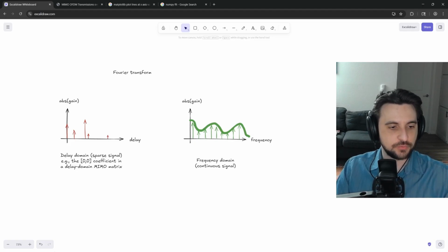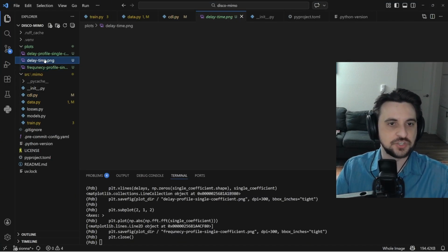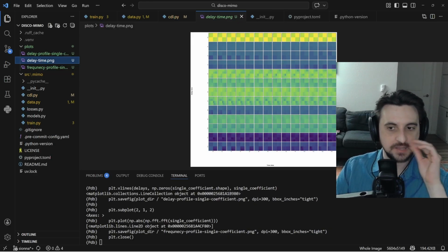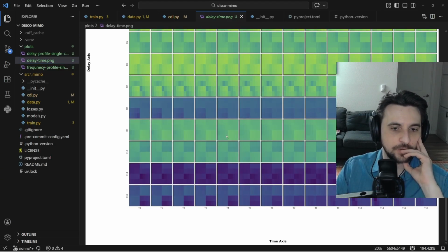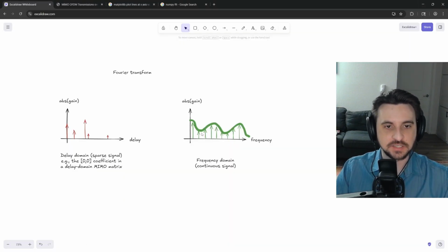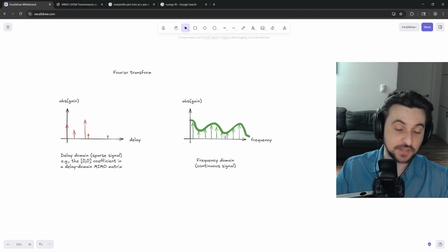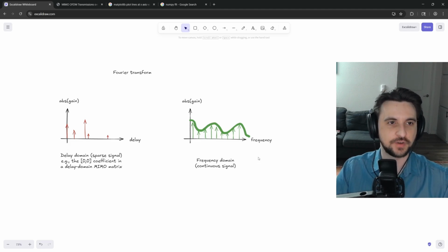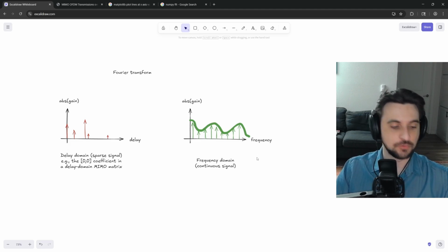So we started with data in a giant grid, and we picked the time point. Okay, then we converted from delay to frequency, and this is called OFDM, which is multiplexing users in the frequency domain. What happens is, these are now 1, 2, 3, 4, I don't know, 5. These are 9 different users. These are 9 cell phones. They're actually 9 cell phones. Like, this is literally how 5G and even 4G worked, and probably nothing's gonna change in 6G.